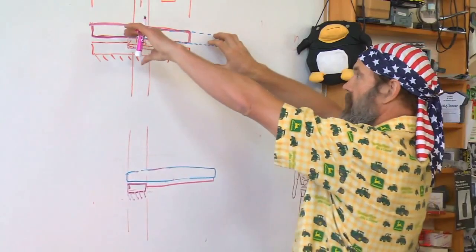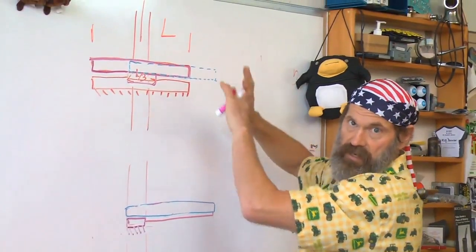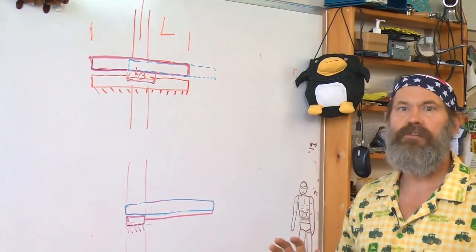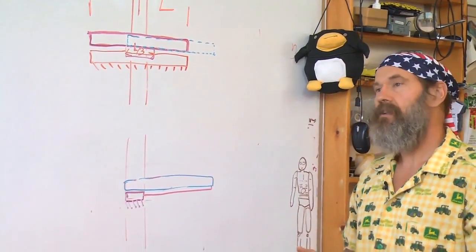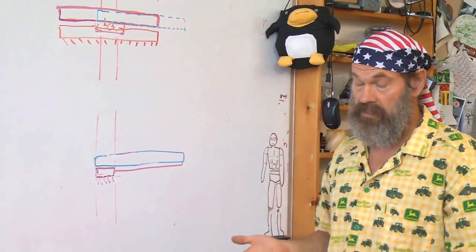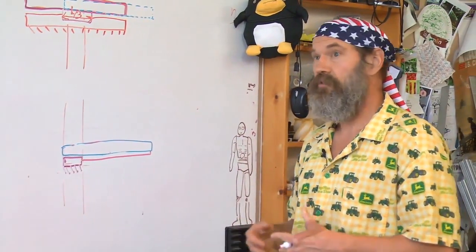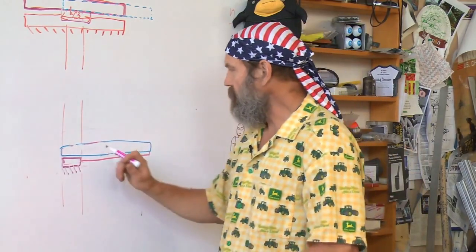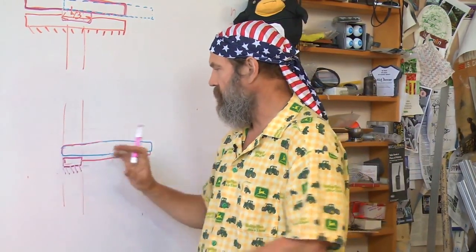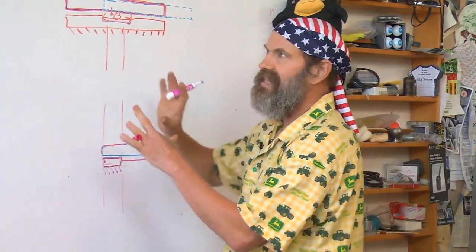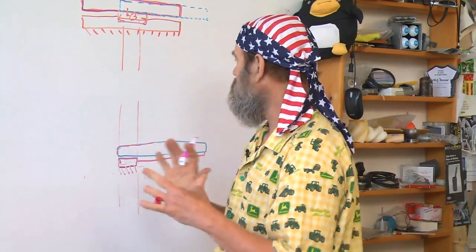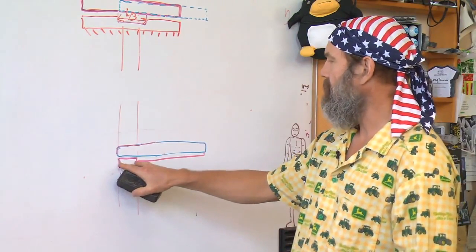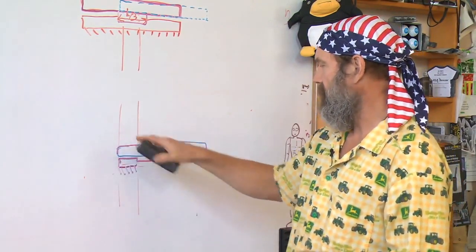You have more bearing blocks. It's a different design like a regular machine tool bed, but this is a drill press. It doesn't need the same stiffness and accuracy of a milling machine. If you needed the stiffness and accuracy of a milling machine in your drill press, it would become a milling machine. So right away you see, by thinking things through with these simple sketches, we're laying out what our machine will be, that this block will be attached to the column.